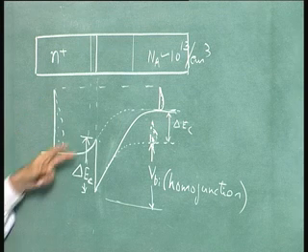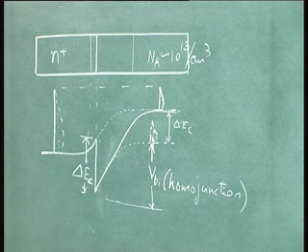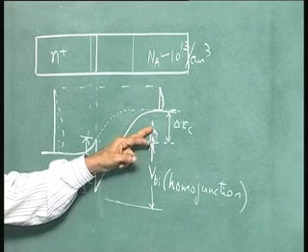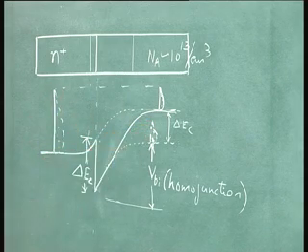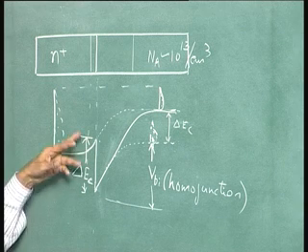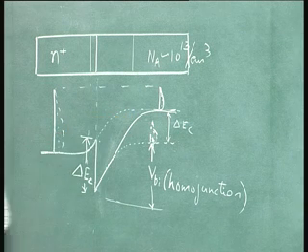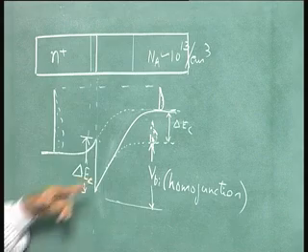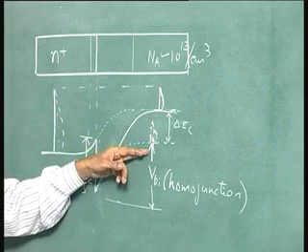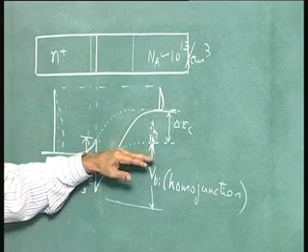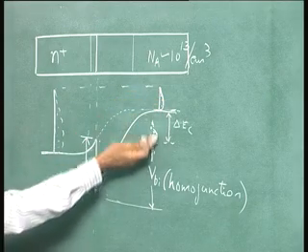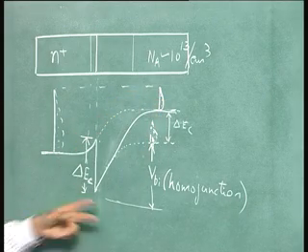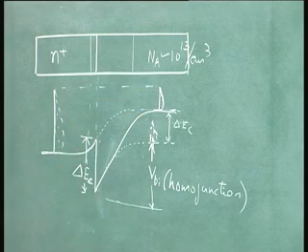That means, because of this notch, if the built-in potential is same as that of the homojunction, there would have been electrons on this side which have higher energy than that. It is not enough just the transfer takes place till that voltage Vt log Nd Na by Ni squared, but more electrons will get transferred till this gets raised up to that point. That is, till this level is shifted up. What would you say now to the built-in potential?